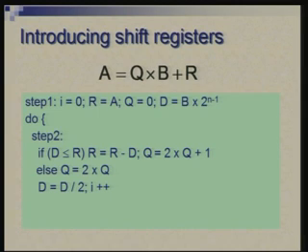So we do d equal to d by 2, and this comparison becomes a comparison of d and r, and subtraction becomes subtraction of d from r. Also, instead of setting different bits of q, we will be shifting q left, effectively multiplying it by 2 and adding a 1 or adding a 0.